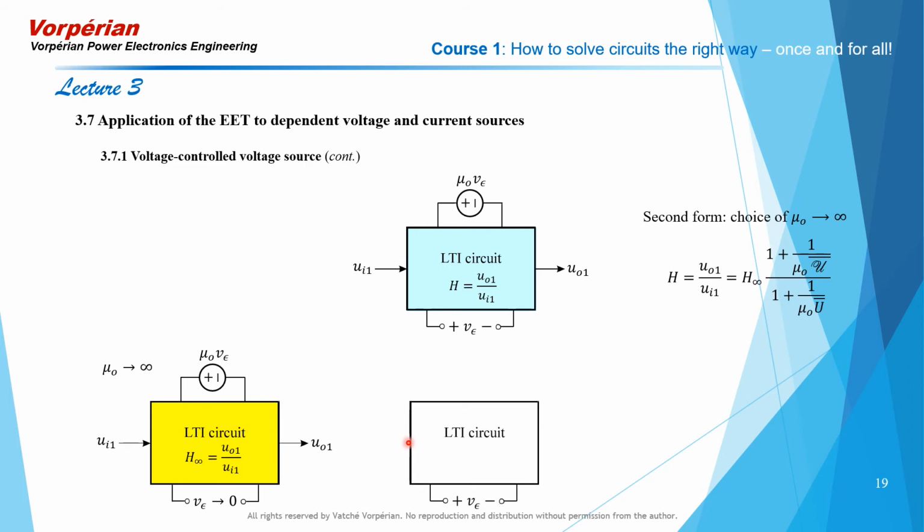So the second computation we have to do is the inverse gain with respect to mu0 with the excitation set equal to 0. In this diagram here, we compute the inverse gain, V epsilon over Vt. We call it inverse gain because really what we're trying to figure out is how much does an independent voltage source connected at this point here talk back to V epsilon, which is the voltage on which this dependent voltage source depends. And now this is our green computation.